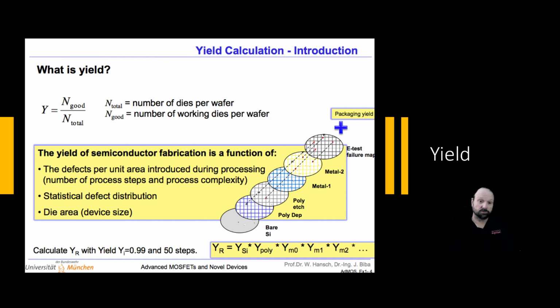And then you're always competing against other people who are also making smaller chips and making them better and yielding higher. Sometimes if you have innovative designs, you can get rid of one layer or two layers and still have a good working chip. And if you have fewer process steps, then the probability of a defect is lower overall.